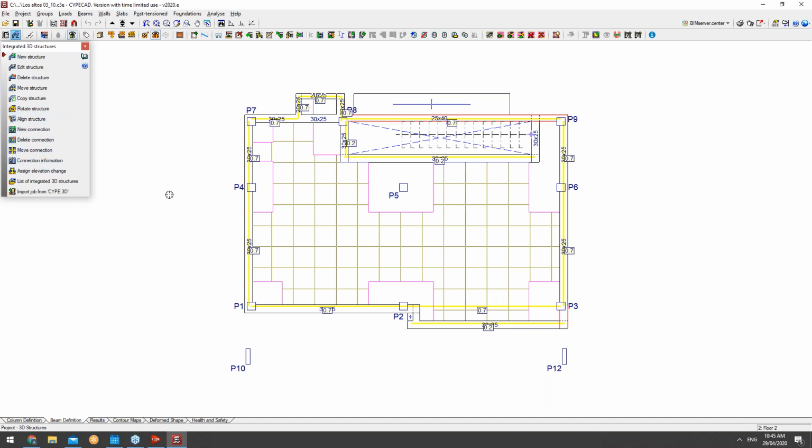And what I wanted to touch on is that when we're dealing with those live and dead loads, those loads generated by our 3D structures, we're also able to bring those in manually if we want to. So if we don't want to bring in the loads prior to starting the program, we have the option to create those additional load cases. And upon those additional load cases, we can bring in the different structures that we want to. Now, that was a little demonstration that I've done in terms of the interoperability with RCC and steel structures.